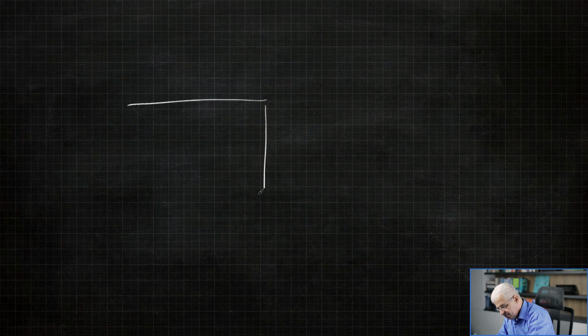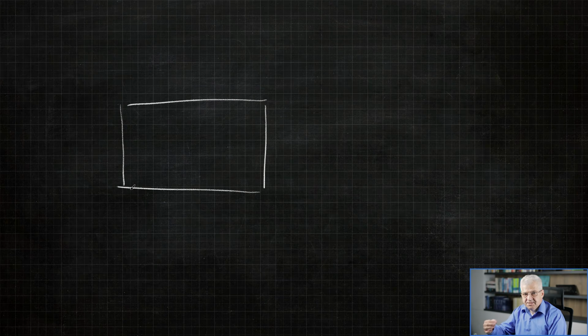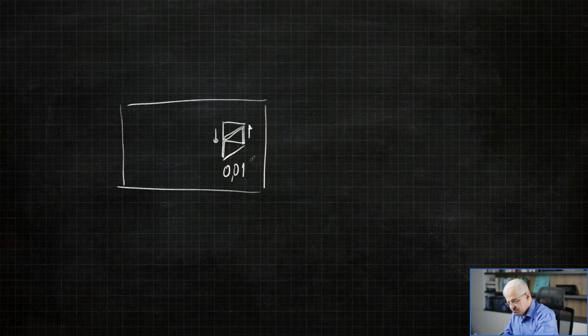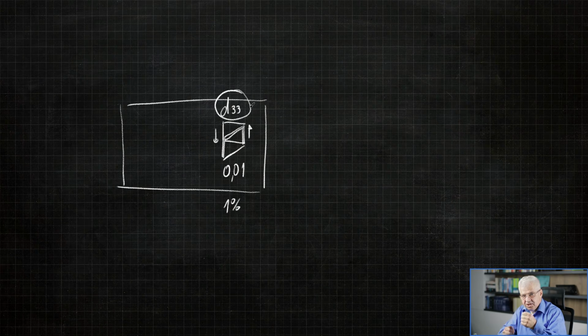Why? Because we have masonry wall, and masonry wall is an orthotropic wall where the shear stiffness in the wall, for this deformation, is reduced by standard to 1%, to 0.01, and the stiffness parameter is the small d33. This is the shear stiffness of the wall. This is reduced.